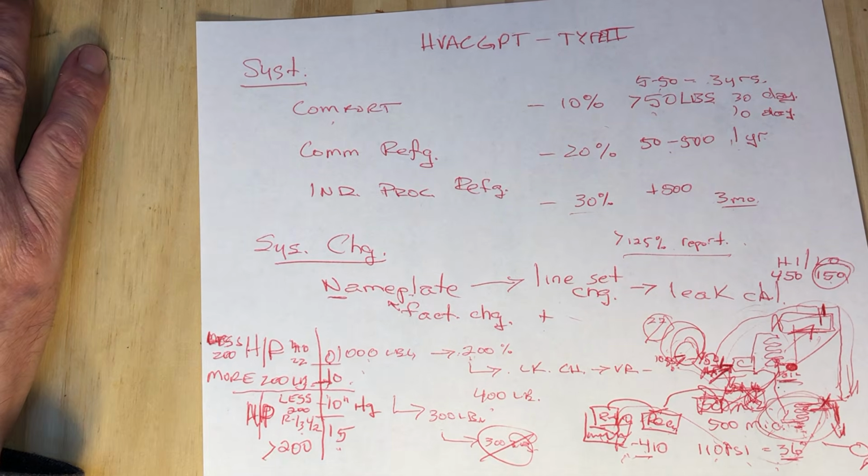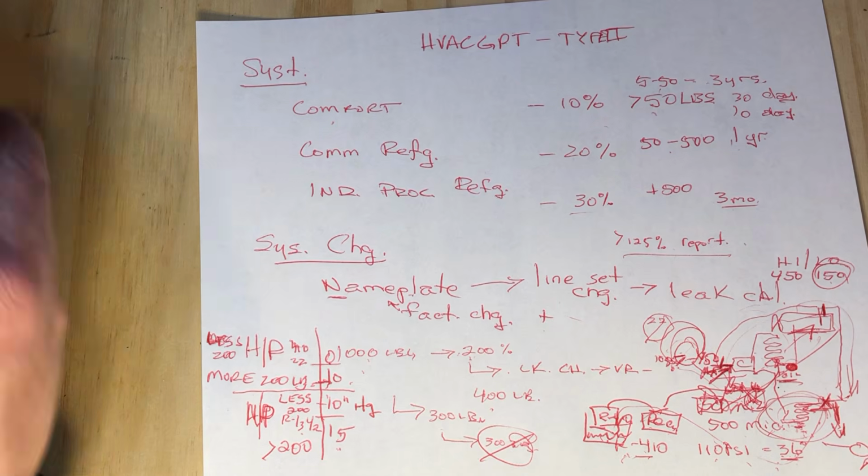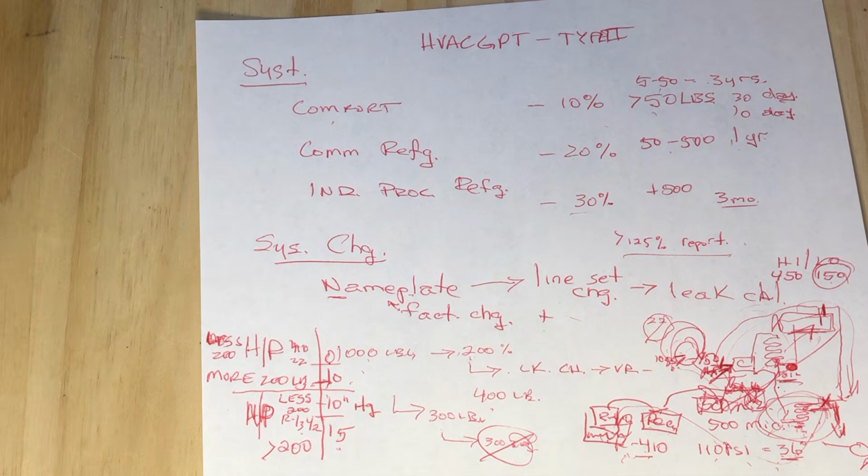So they might have a question where they're saying, hey, you've got an R134A system, it has 300 pounds of refrigerant, what are you going to get your required vacuum rate down to according to the ARI? And that's what this is. This is the AHRI, now 740 standard, talking about your recovery equipment being able to get down to these levels before they can open the system for the purpose of service and repair.